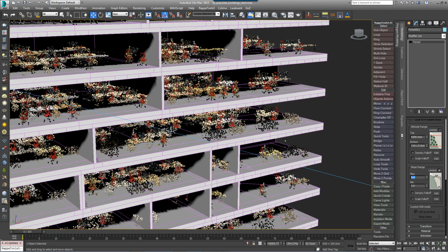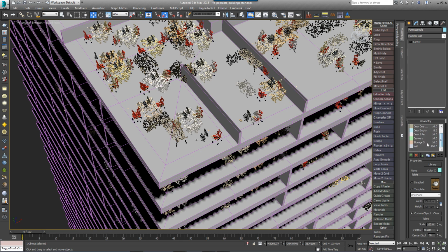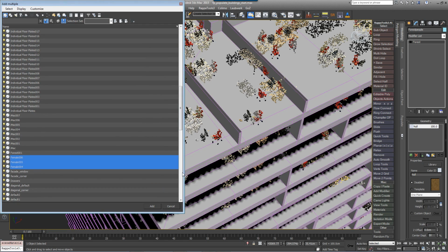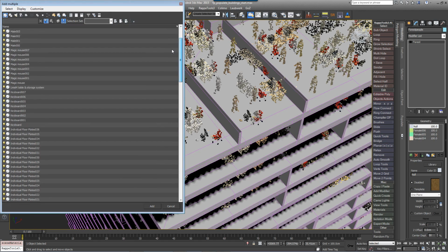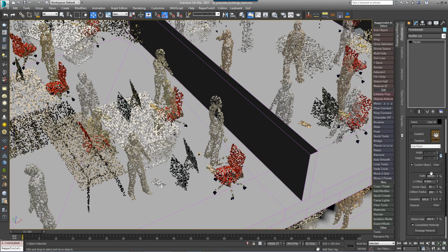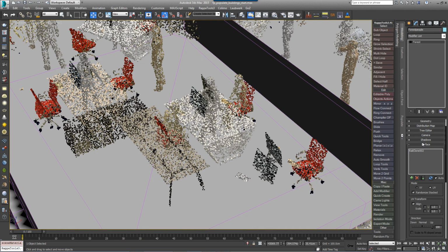We can now reuse this forest object to add the people. To do this, clone it, then go to the geometry rollout and delete all of the items except null. Click on add multiple and pick the male and female characters. Adjust their probability until you get a good distribution. A low value of 2 or 3% works quite well. Because we duplicated this forest pack object from the desks, they share exactly the same distribution points. This can result in characters stood in the middle of desks, which we don't want.